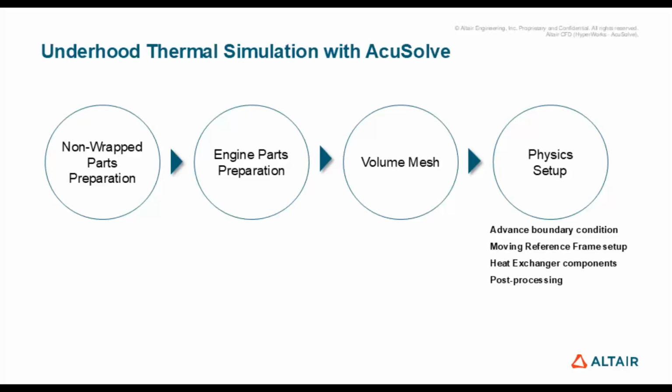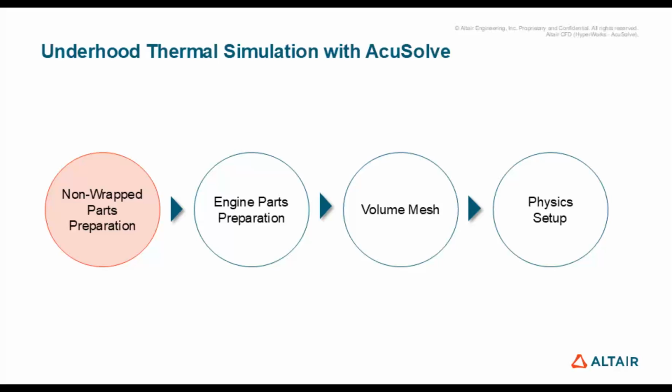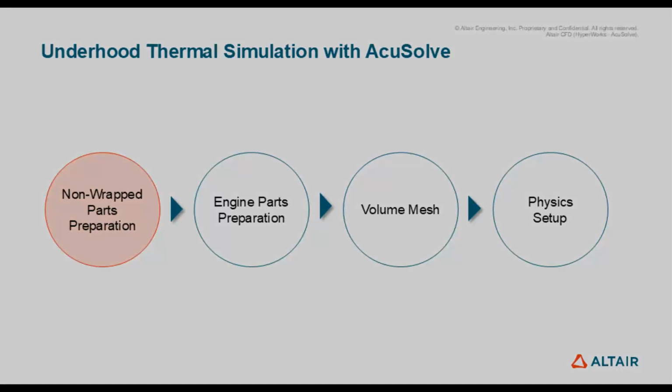In the fourth and final video, I will set up the flow domain, the heat exchangers, and the moving reference frame. After running the solver, I will post-process the result from AcuSolve. Now let's get started with our workflow with the non-wrapped parts preparation step.